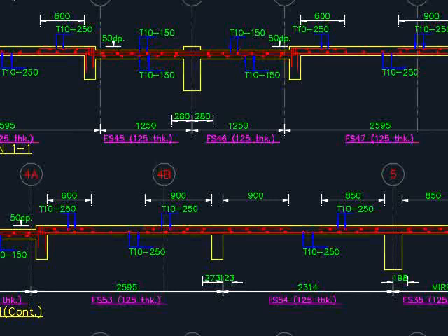However, if you choose to have the reinforcement bar to be continuous, you need to make sure that the length of the reinforcement bar should not exceed 12 meters. Otherwise, the lapping will be required.